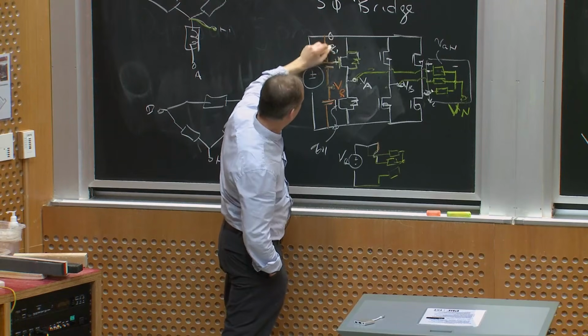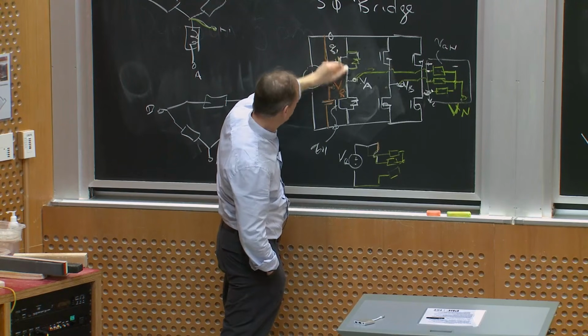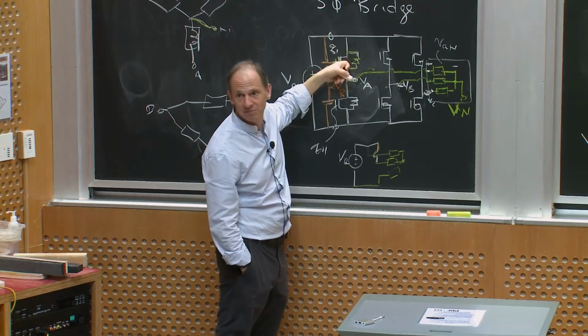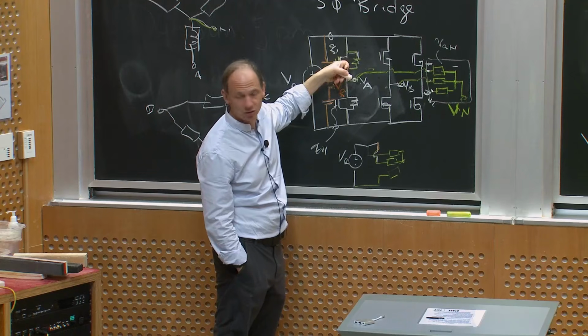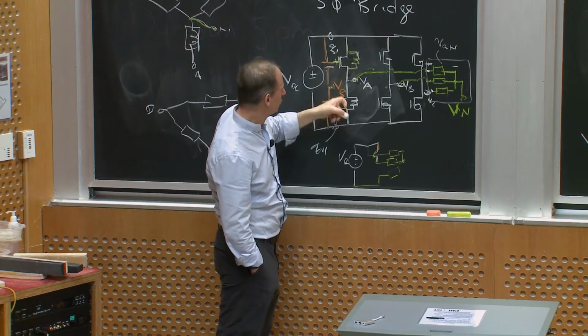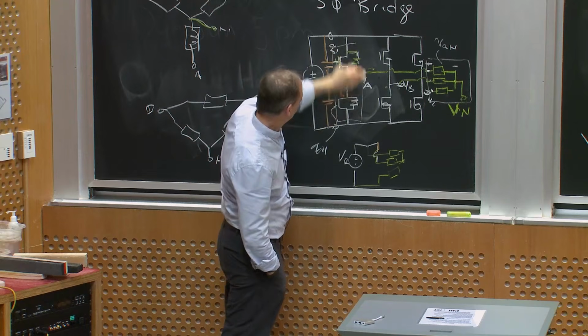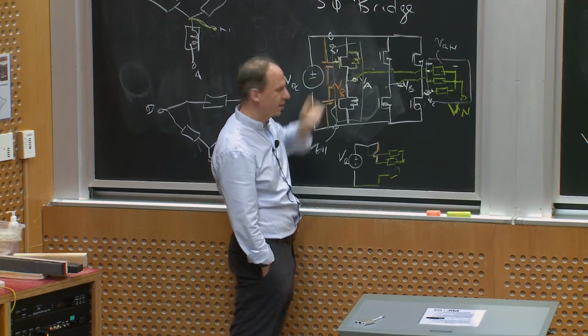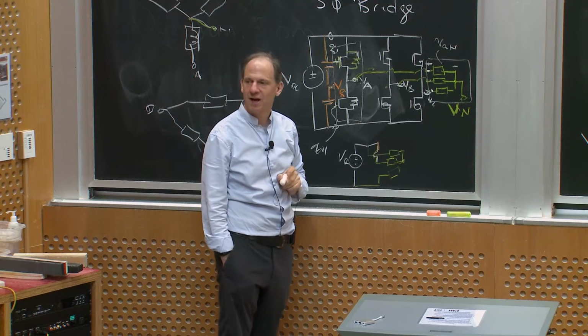The average value of Q1 over a cycle is the duty ratio of this switch. So at modulation index of 1, the duty ratio of the top switch goes to 1, with what I've told you so far. So I could talk about the duty ratio of this half bridge just like it was a buck converter, where I'm talking about the on-state fraction of the top switch.